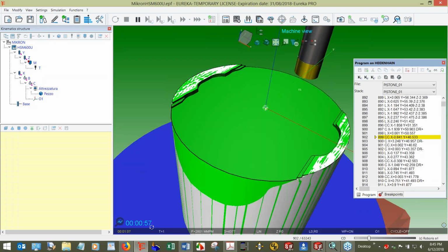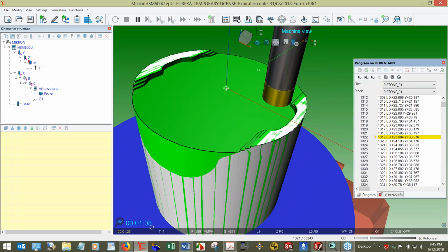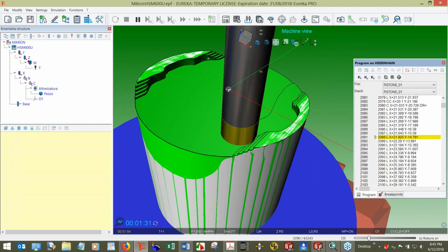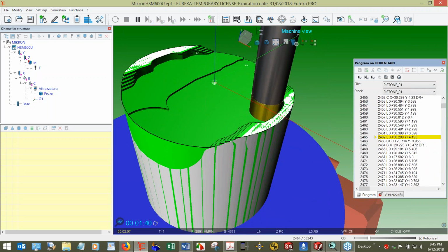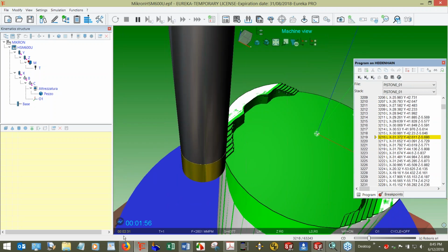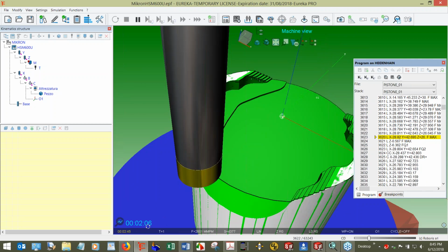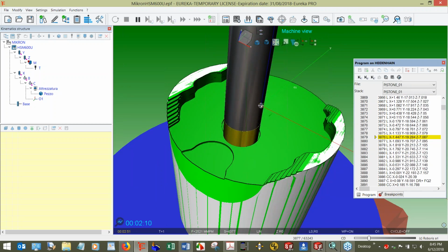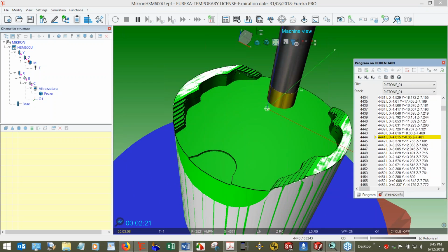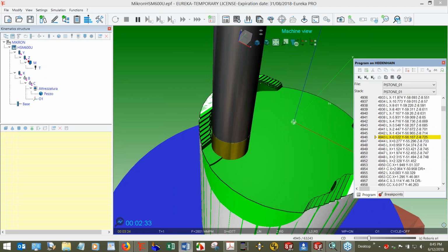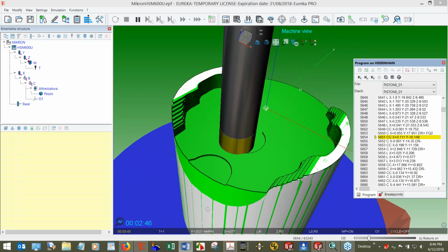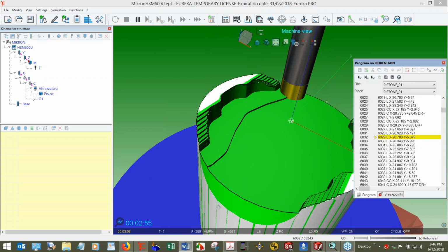So I said, okay, you can go as much as 20% faster. It's looking at everything. It's speeding up the time that you would be in air and actual cutting also. So you can see it's like 2.5 minutes versus 2 minutes. I run this out and get to a cycle time of almost 11 minutes versus 14.5 minutes. So it really knocks some time off of it.